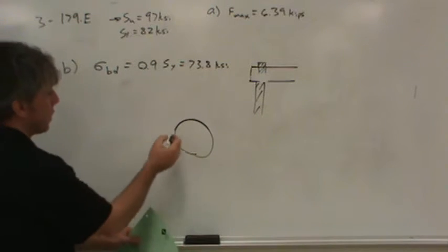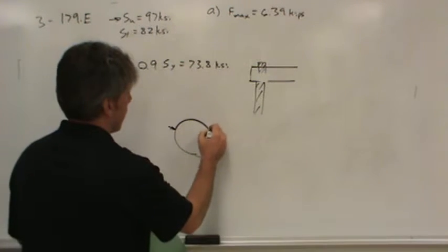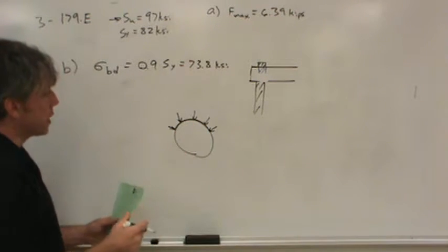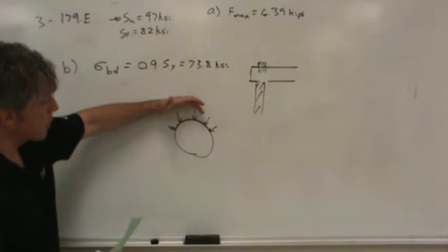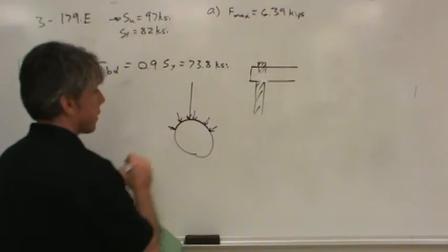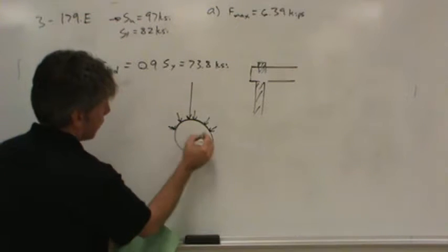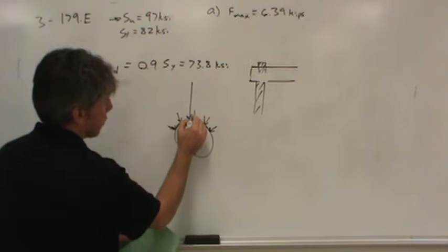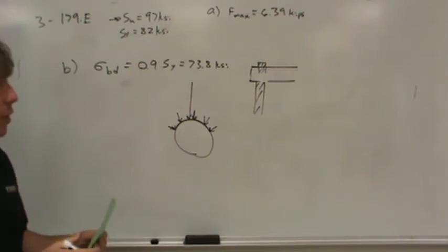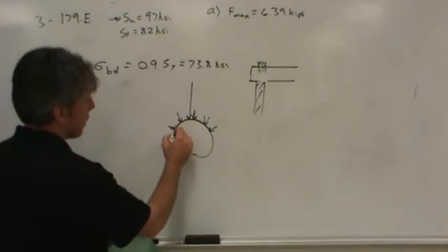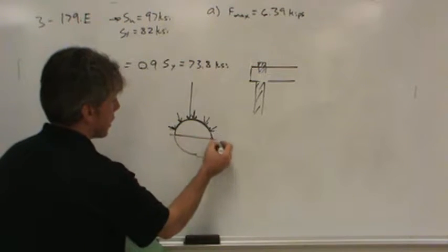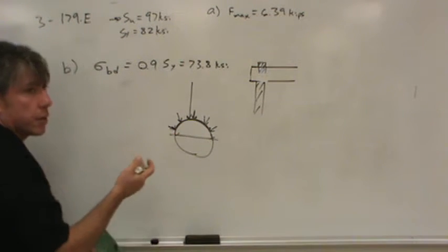In that case, it's as if there's pressure applied to the pin. Now, the force that's actually being applied as an integral of all this pressure, that force has only one direction, right, like this. So it's just a component of the pressure over here. It's a larger component here. Here it's almost all of it, okay? So how do you deal with that? Well, the way you deal with it is instead of considering the area all the way around 180 degrees, you take the projected area. And this is fairly common. You'll see this in other classes.